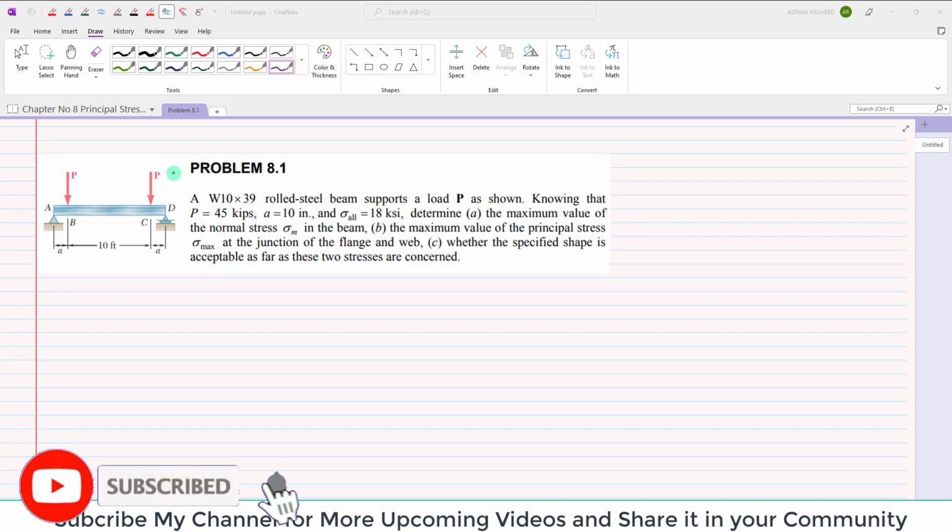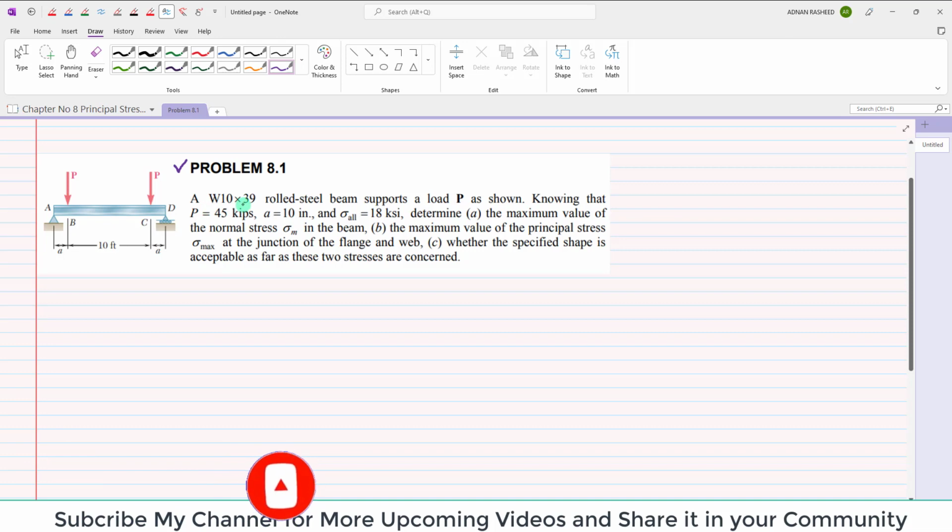Bismillahirrahmanirrahim. Welcome back. Problem 8.1. In this problem, it is given that a W10 by 39 rolled beam supports a load P as shown. You can see this is a beam AD and it supports a point load at points B and C. Knowing that P is equal to 45 kips, a is also given, that is 10 inch. The distance from B to C is 10 feet. And allowable stress is 18 ksi. So determine the maximum value of normal stress sigma m in the beam.